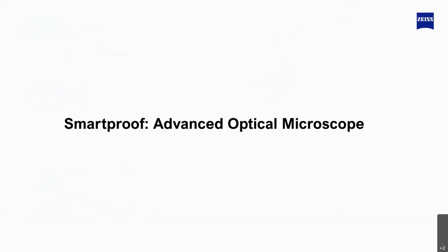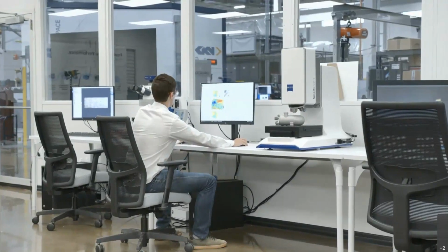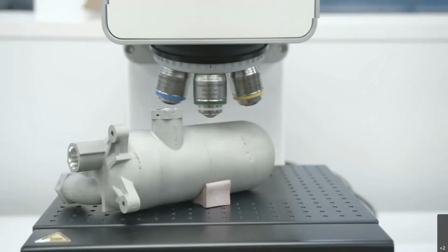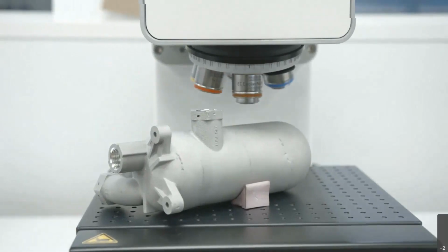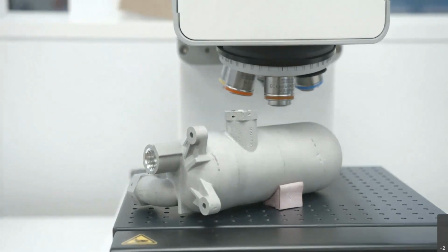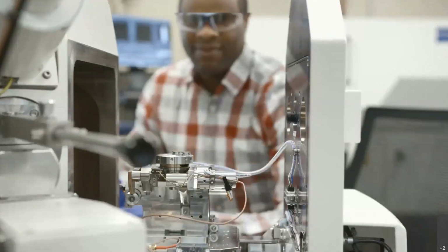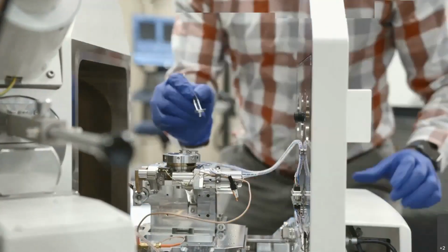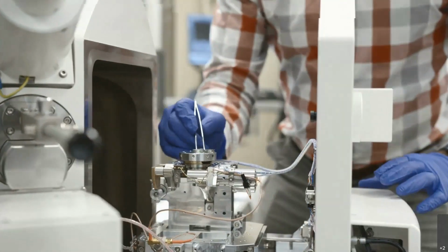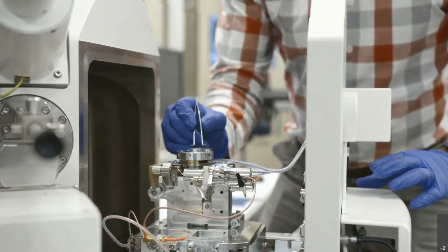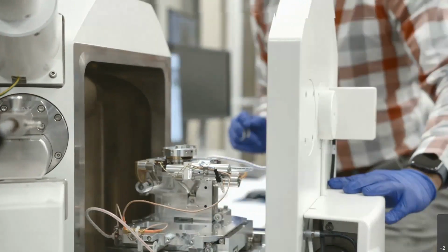So you're looking at the whole part, but you're able to show much smaller size pores. And after having seen small size pores, if you want to understand surface roughness, we have different solutions available. One of the solutions I'm showing you here is confocal optical microscopy. We have laser confocal, and X-ray CT is also used for measuring surface roughness, but on the inside where a light or a probe cannot touch. And then we also used SEM to understand the chemistry as well as the grain structure of this part. After having shown all the measurement side of it, I can now walk you through the results that we got using all this equipment.